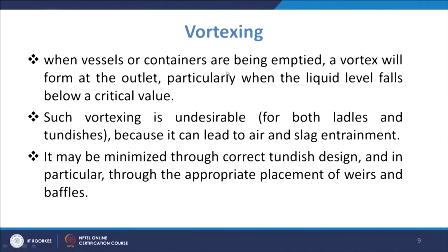This vortexing we can minimize through correct Tundish design, and in particular through the appropriate placement of weirs and baffles. So, vortexing can be minimized if we have proper Tundish design, as well as the Tundish furniture we use, that is your weirs, baffles or dams.